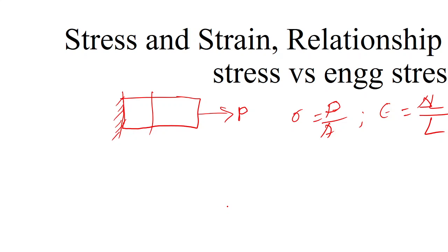So the first thing we will try to do is obtain the stress strain curve of the particular material. After loading the material onto the UTM machine, the calculations are, for example, the engineering stress is defined as the load divided by the original area A naught. Whereas the true stress, denoted by sigma t, is equal to the applied load divided by the instantaneous area Ai.